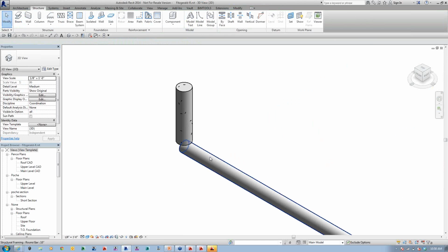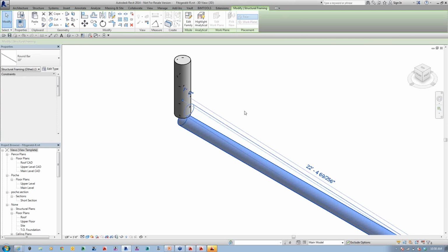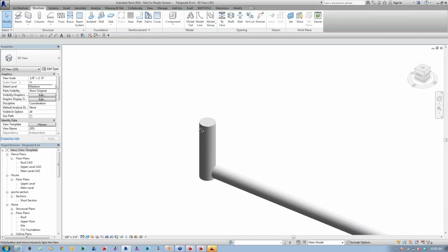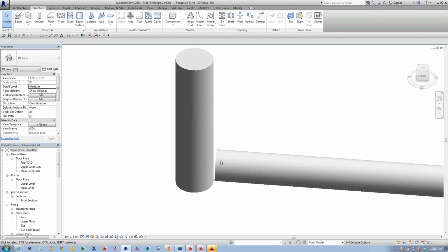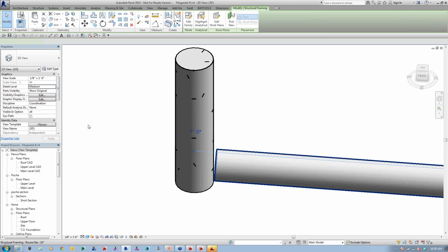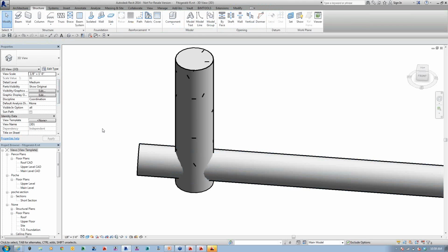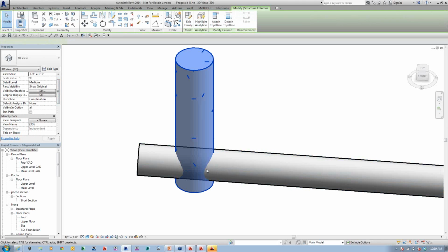Yeah, I got these two different columns in here, and granted one's concrete, but maybe I go in and move this up a foot inside. Well, they won't ever cope together. They stay apart, and even if you start messing with the beam family themselves and start messing with the offsets and stuff, and maybe you're going to go in and make the extrusion 2 foot inside, we can start to get some of that in here, but sometimes I find that these will break over time. They start not to clean up together.